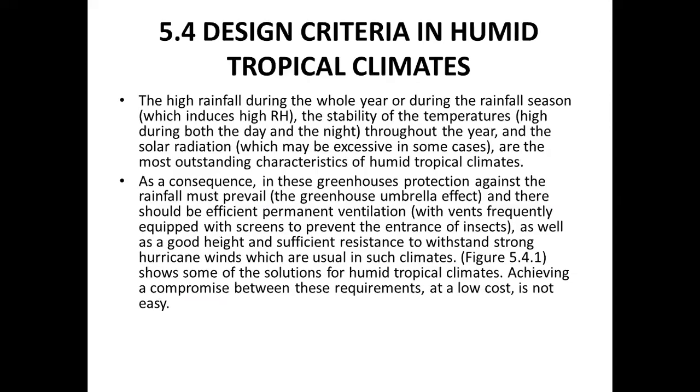Design criteria in humid tropic climates. The high rainfall during the whole year or during the rainfall season, which includes high relative humidity, the stability of the temperatures, high during both the day and the night throughout the year, and the solar radiation, which may be excessive in some cases, are the most outstanding characteristics of humid tropical climates.